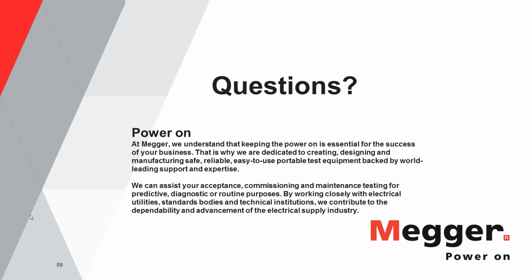That's a very good question, because obviously if we can cut down the number of tests, it would certainly help us improve the efficiency and make sure that we get the job done quickly. But think of this from a system standpoint of view. When we talk about primary injection testing versus secondary injection, if you do the secondary injection testing, you can still verify that the trip unit is working, but in reality, you're not checking the complete system, which is the breaker operation and the operation of the trip unit.